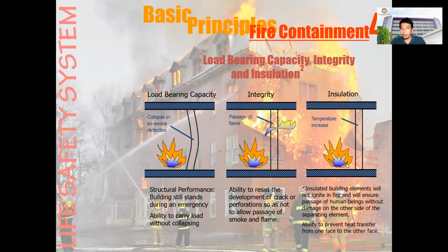Next is insulation. So temperature increases. Insulated building elements will not ignite in fire and will ensure passage of human beings without damage on the other side of the separating element. Ability to prevent heat transfer from one phase to the other phase. So normally we use concrete material.